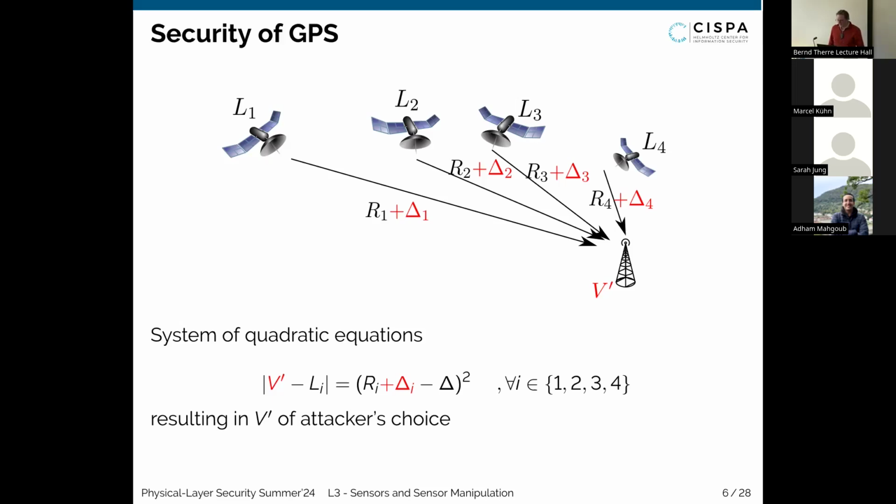This is a simplification here, but all these signals essentially have to be processed in parallel by the receiver. We are not talking about discrete messages that start at some point and stop at some point, and then we have a large gap. This is a continuous stream of information coming from the satellites. So even for 4 satellites, we essentially have 4 parallel receiving pipelines in our GPS receiver that each listen on a specific channel. Each of the satellites has its own channel, like its own frequency. So even for only 4 satellites, our receiver has to follow at least 4 satellites separately in real time the whole time.